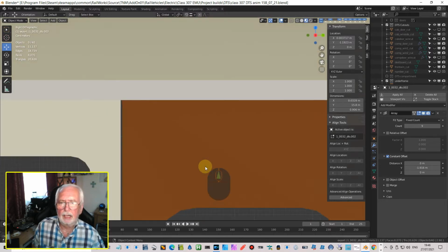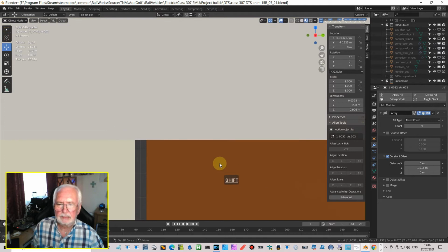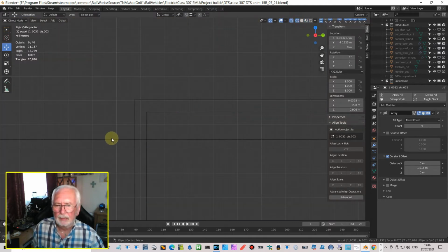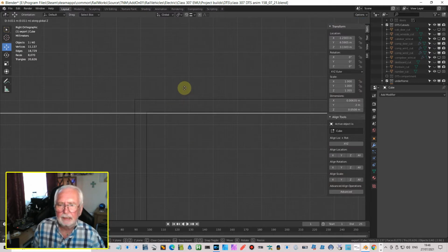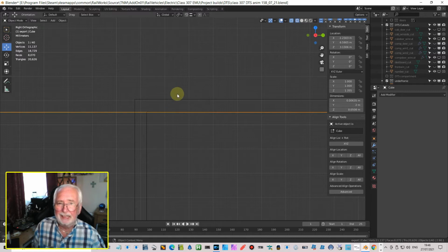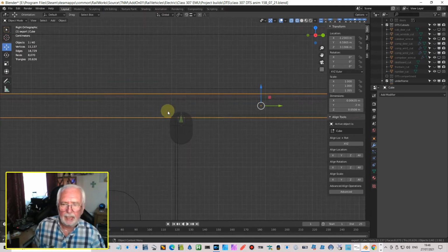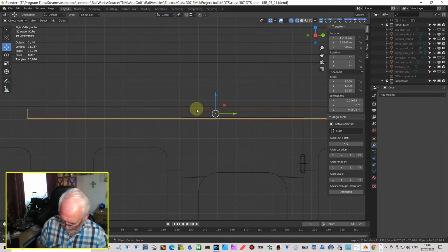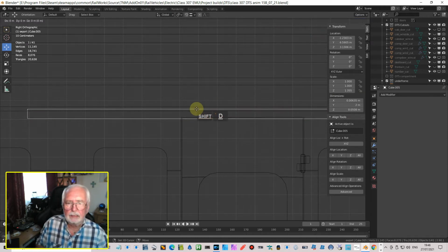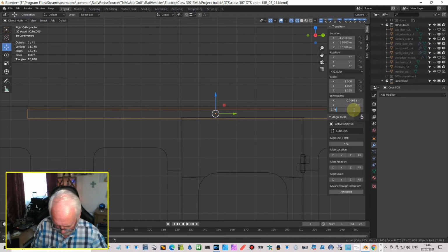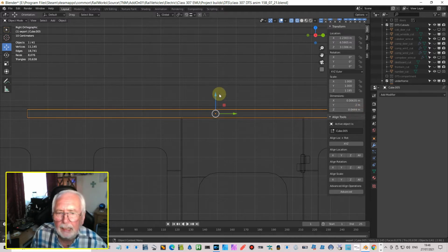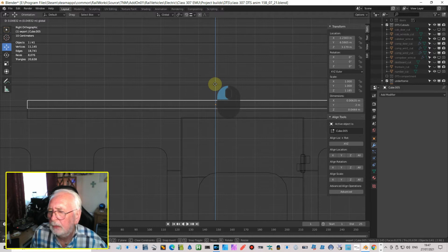Face on again. Okay. Right, so now we need to make sure this beading here is just, grab Z, just covering that gap. So this is forming an inner sill, if you like. So that gap between door and cutout, this will form the sill. So that's okay. Now let's add another bit above it then. Let's duplicate that. Make this 1.75 inches, and let me just move that up so it's there.